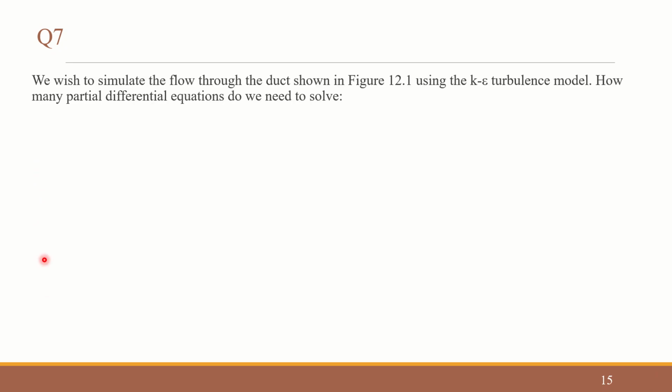Now we are going to question 7. In question 7, we wish to simulate the flow through the duct shown in figure 12.1 using the K epsilon turbulence model. How many partial differential equations do we need to solve?